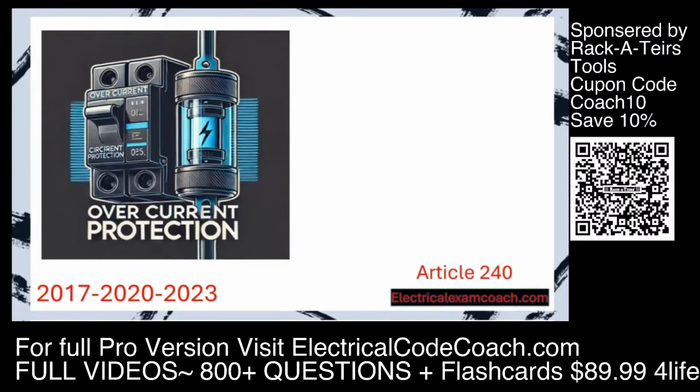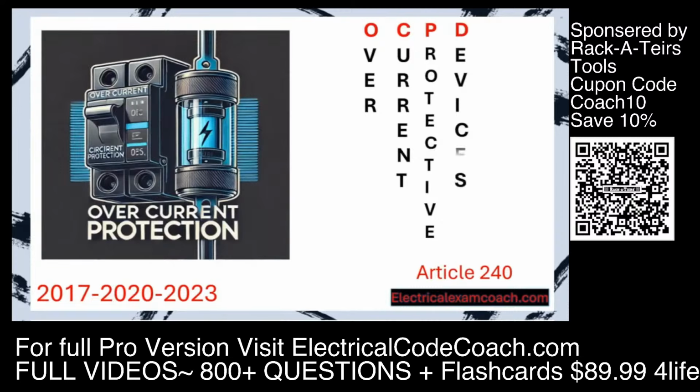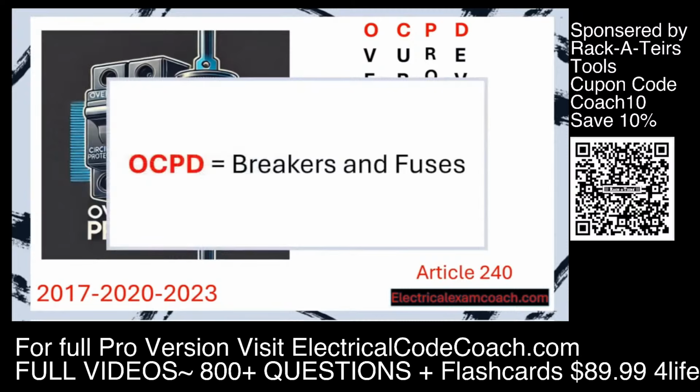We're going to be in Article 240, and we're going to be learning all about overcurrent protective devices. You'll hear me use the term OCPD throughout the rest of the program, and all it stands for is overcurrent protective devices. But to simplify it even further, just think about it like this. Anytime you see OCPD, it just means breakers and fuses. Whether it's the individual breaker at a branch circuit, 20 amp, or it's a 100 amp feeder breaker, or our main 200 amp disconnect, it's either going to be a breaker or fuse, and they're all OCPD.